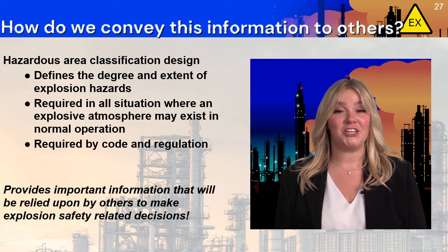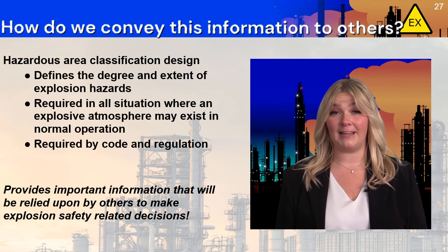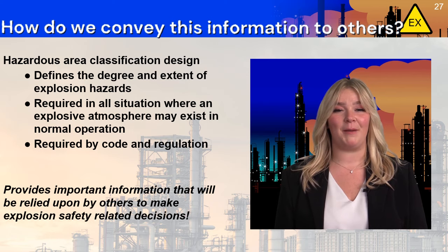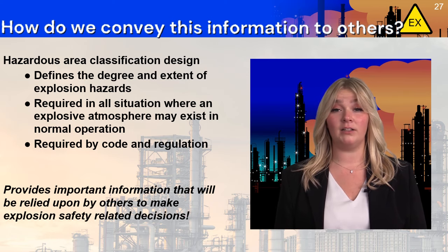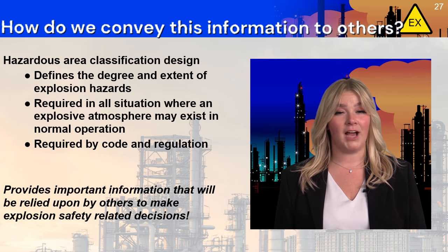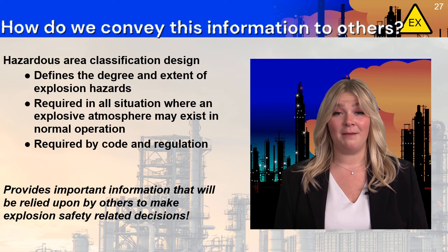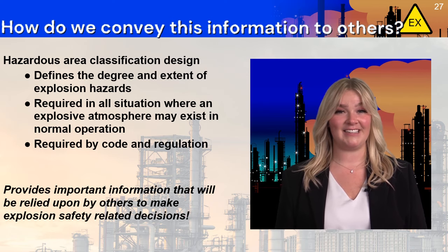A classification design is required for all situations where there may be a flammable atmosphere in normal operation. It's required by national regulation in most jurisdictions. A classification design must be clear in intent, provide all necessary information, and be documented in a format readily understood by all parties. Many people will use this information to make explosion safety-related decisions.